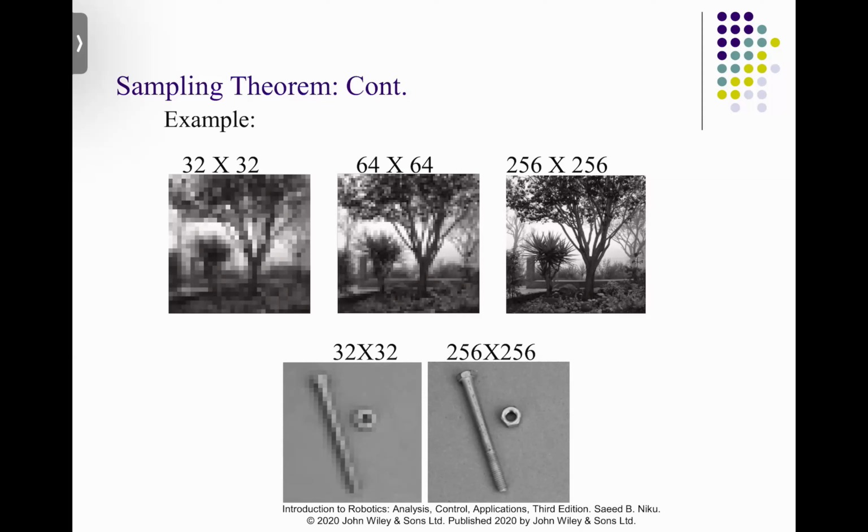You can't capture the whole signal, but you can increase the sampling frequency. But if you increase the sampling frequency, that increases your storage requirements and your power requirements. For example, if you have a signal at gigahertz, clearly you need a sampling frequency of twice gigahertz. So the equipment cost also increases.